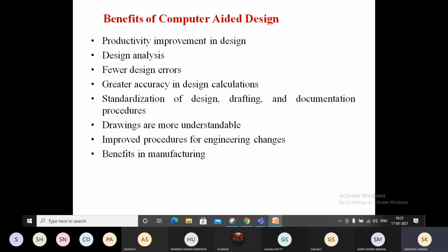Now a simple example I had taken, a stress strain analysis of our specimen. For the stress strain analysis of the specimen, you have to take a rod, get it down to the required dimensions, do the machining, hold it in the universal testing machine, conduct the experiment and get the information. It will not take a few minutes, it will take a few days or a couple of days. Okay, it is a destructive testing.